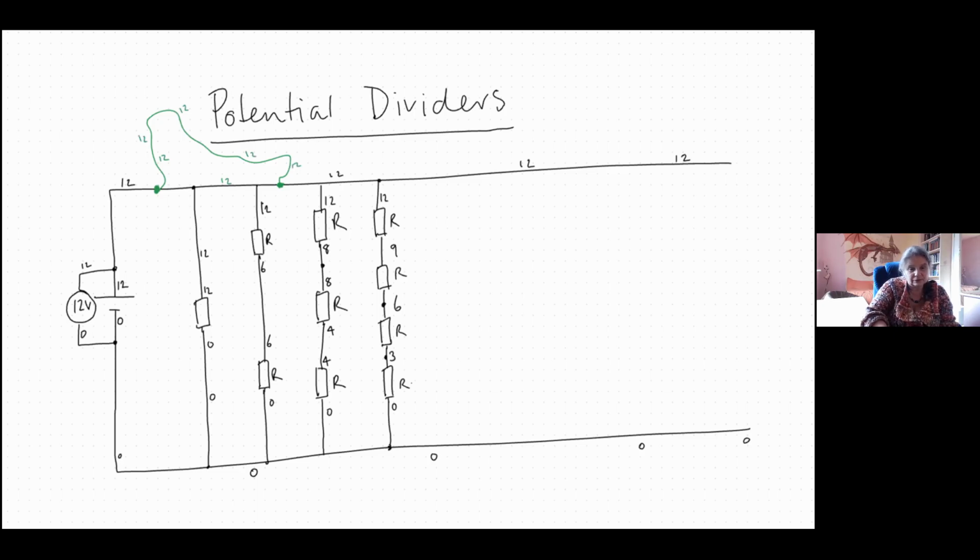And because the wire, the black one that goes straight along the top, has no resistance, not just a small resistance, no resistance, adding the wire in parallel doesn't reduce my overall resistance. So will that green wire that I have put in there do anything? Will it change anything? No, it won't. It will do nothing.